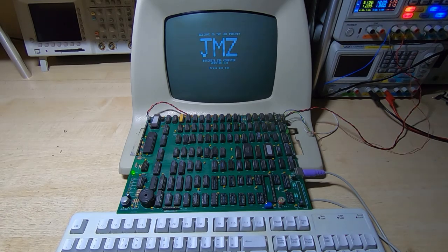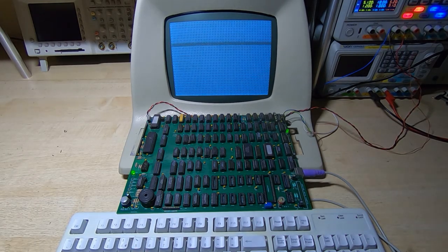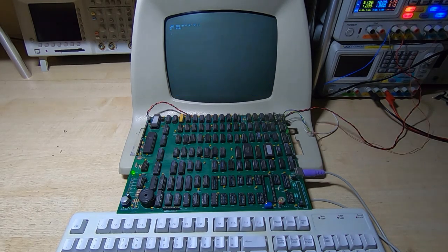And we're certainly getting something on the screen. It looks fine. We'll try dumping the ROM again. You can see how much faster it is at this speed. We'll run the self-test. Should complete a lot more quickly. We'll see the LED should only stay on about half the time, which it does.